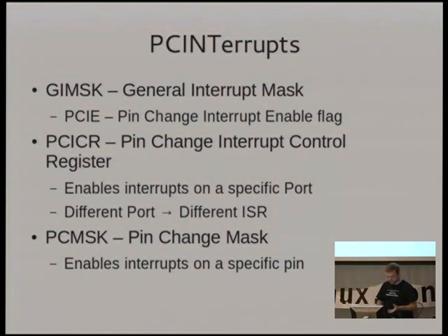So, pin change interrupts. There are a few different registers that you need to worry about to deal with pin change interrupts. You have the general interrupt mask, which says whether it's going to deal with pin change interrupts at all. You have a pin change interrupt control register, which controls which ports interrupts are enabled on. And then you have a pin change mask, which decides which pins interrupts will be triggered for.